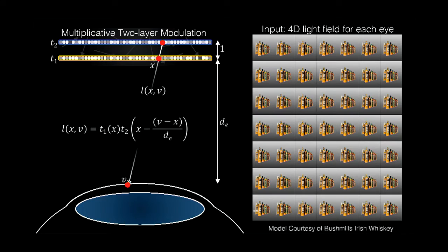So now, why can we get away with these 2 layers of LCDs? Well, the thing is, these LCDs are multiplicative. So the rear layer here will emit light, and then the front layer can block the light. So along any ray, you multiply these two values because each of the pixels are basically programmable attenuators. Right?